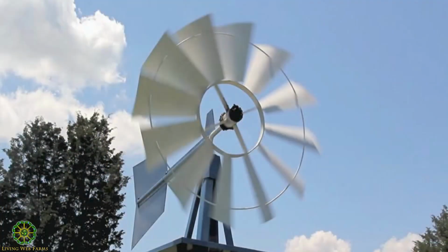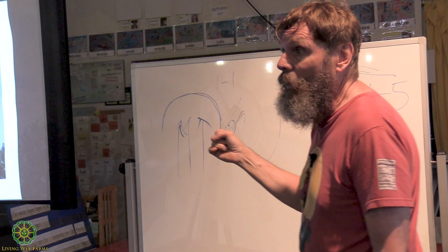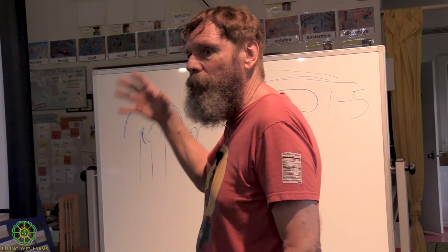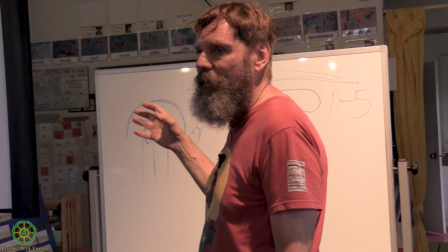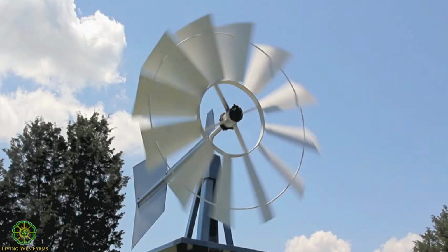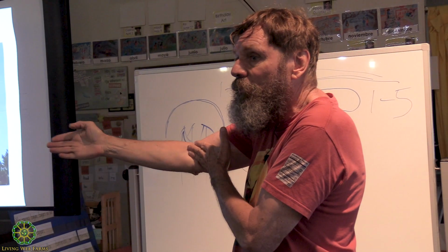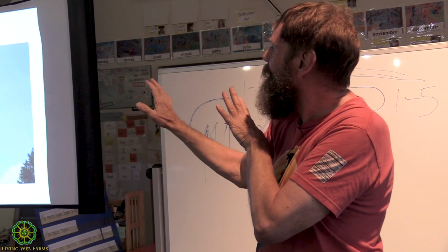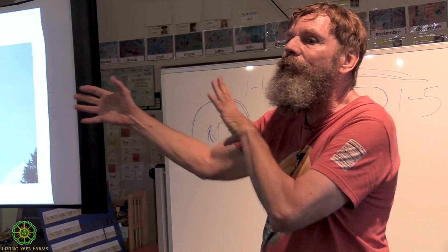Let's go to the next one. Another thing here, multi-bladed turbine like we have, Aermotor, and others. People make water pumping mills. They're really nice because they have a lot of power to them. They do take a little bit to start up, as I said before, and they're not made for extremely high speed, because they can vibrate. In which case, that tail is designed to fold, and it actually hinges, and it turns the business face of the wind turbine away from the wind, so it slows it down.